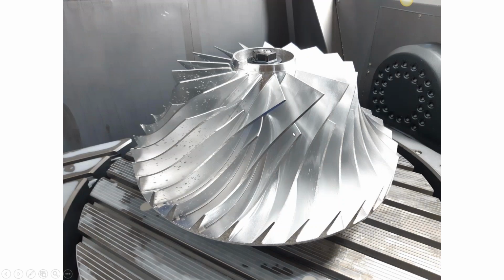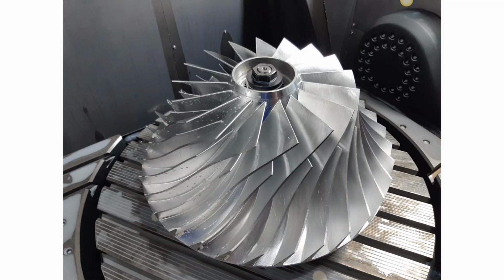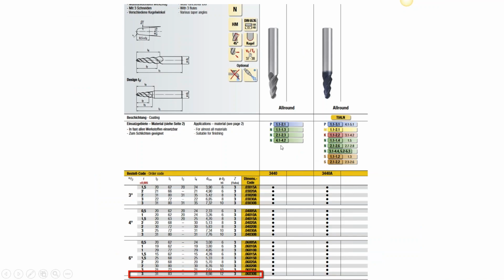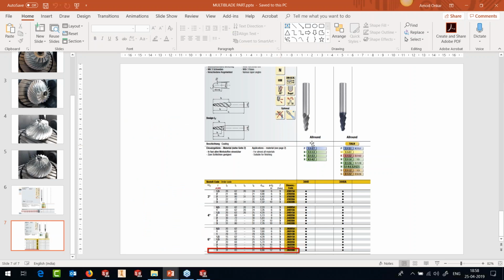Okay, so we did this excellent machining with SolidCAM's multi-blade capabilities, and we were at par with our competition, the best players in the market for machining such parts. This part was done completely using SolidCAM's multi-blade machining technology, and we used the tools from Moog. We used two different tools. One was a 12 diameter taper ball nose with 4 degrees taper, and bulk of the roughing was done by a 10 diameter 6 degree taper tool. So we used these excellent tools to machine, and the result also was very nice. We were at par with competition.